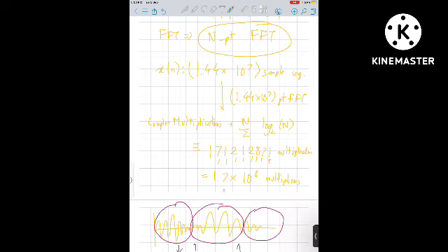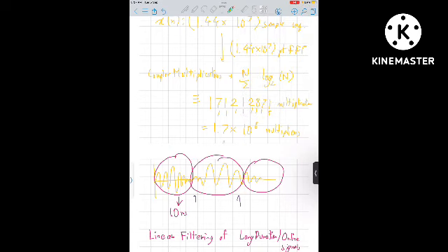So what we actually do is that when we have this long signal, we break it into several individual blocks of very small length, some 10 milliseconds, something like that, and then we process these blocks individually. That's why I said it's a technique of linear filtering of long duration or online signals.